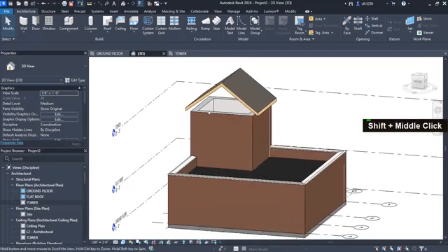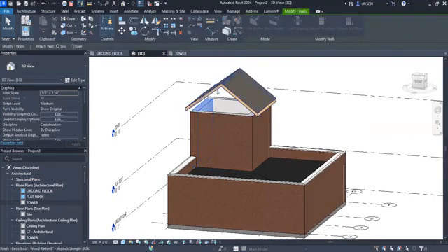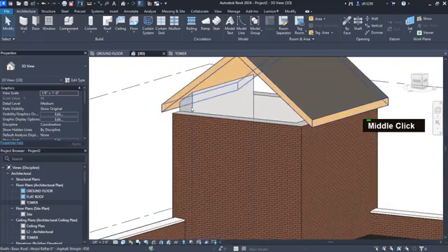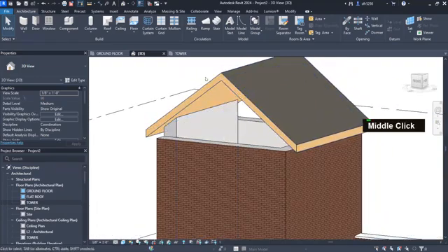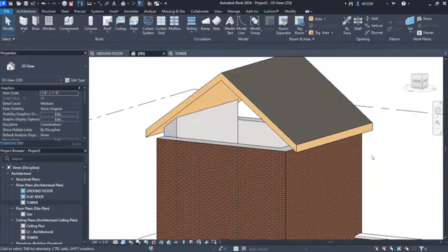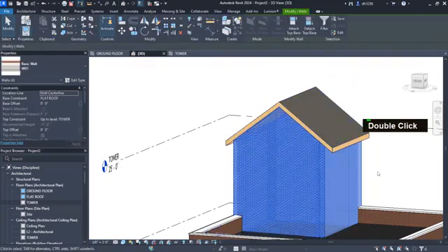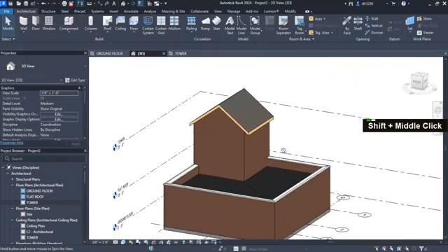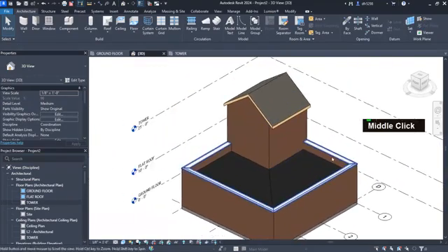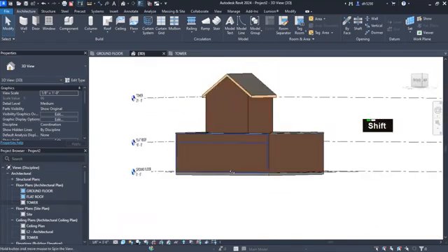And then the tool that you're going to use is you're going to click on the wall, and you're going to use the attach tool, click on the roof, and that's going to bring the wall up to whatever surface you have. So the roof here has this slope. It's going to perfectly cut the line to match the roof. And last thing that you have to do is essentially do this to every wall. So drag across to select them all, and then you have it. There you have it. You've finished the first part of this model. The building's completely enclosed.